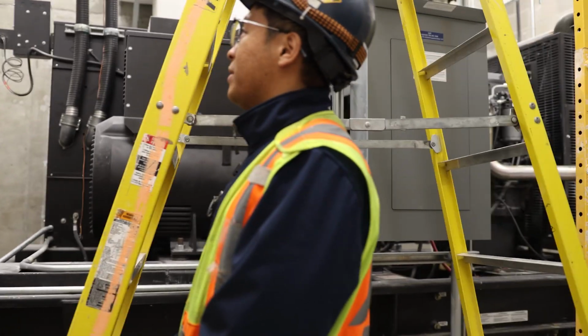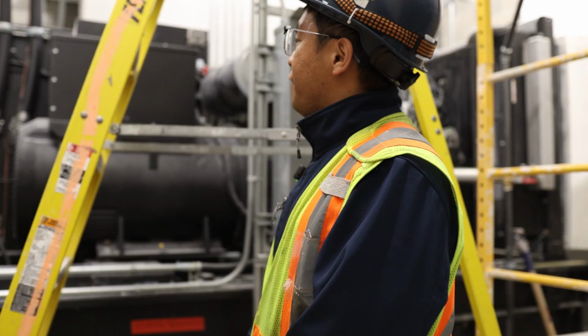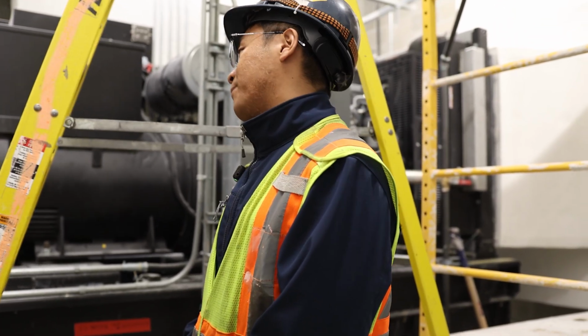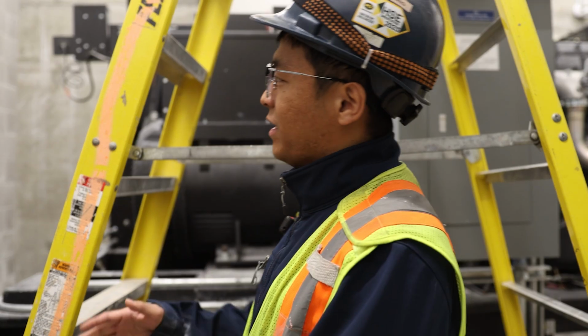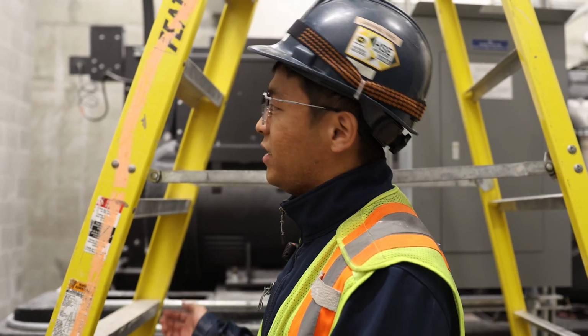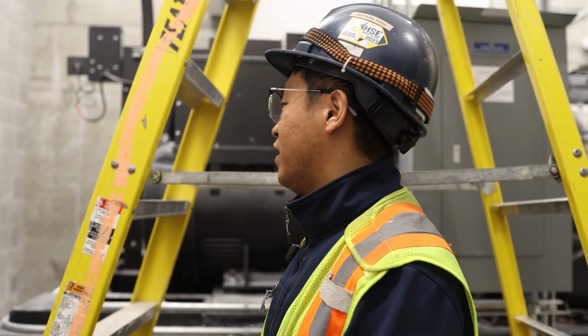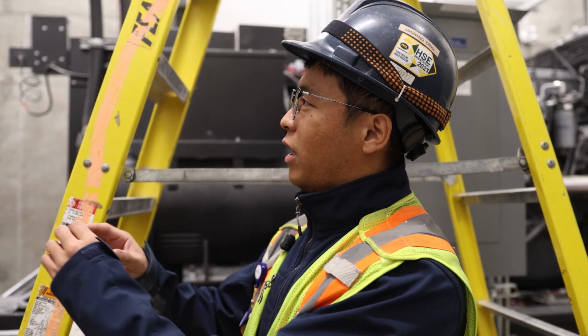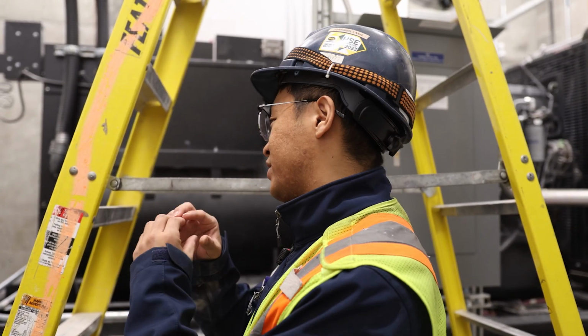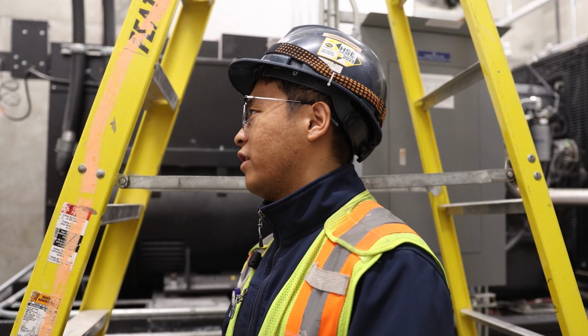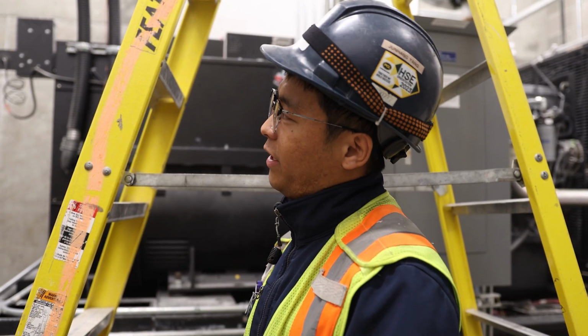If the damper doesn't open, we will see a damper not open alarm. That means if the BMS is trying to open the damper, but the feedback from the damper is still showing it's closed, we will see the alarm on the BMS. On the graphic, there will be a box. The background will be red, and it will say it's in alarm. And also the alarm console will show it.